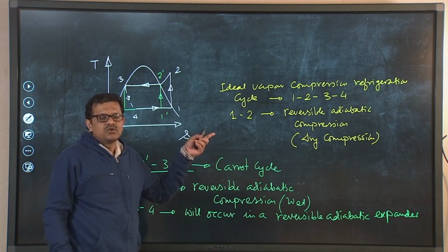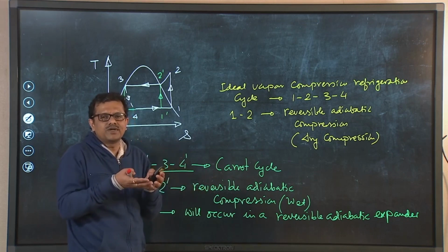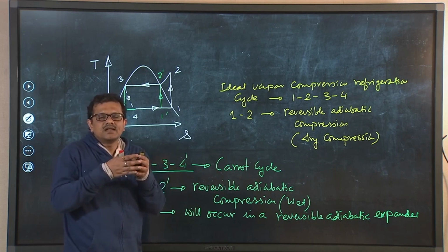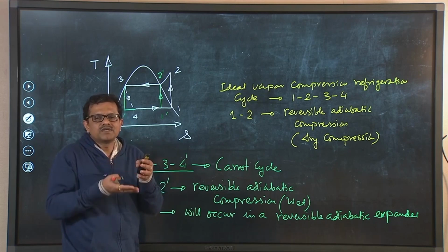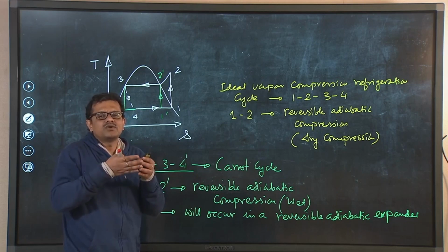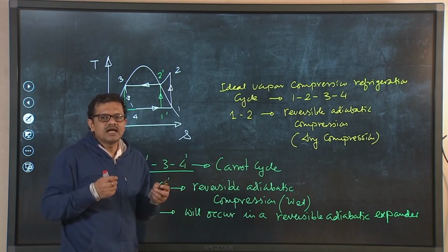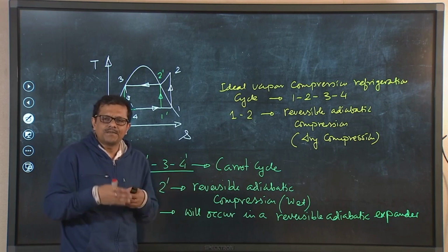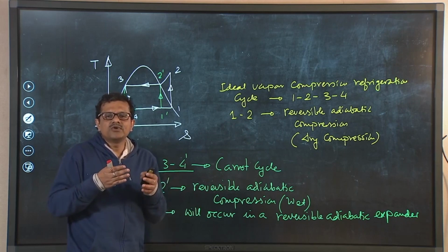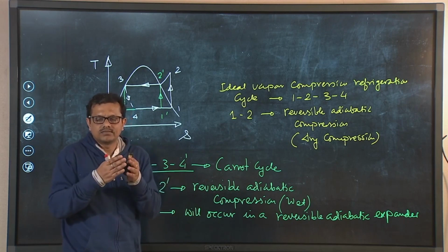So, liquid will now rise with the piston, that is, the working fluid will now be compressed. The liquid refrigerant in the cylinder head, when the piston is rising, will damage the valves, etc. Not only that, as I said, liquid and vapor are compressed differently, and a liquid phenomenon will occur wherein liquid molecules will try to penetrate into the gap between the piston and the cylinder wall.